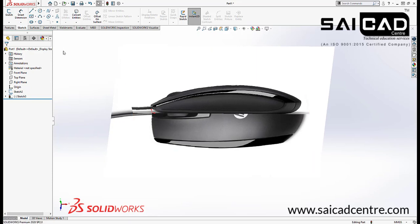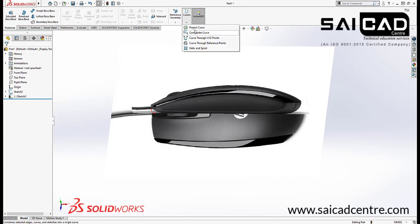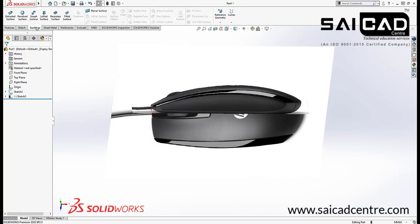So till now in solid modeling, most of the students or most of the people only use the line, circle, these commands, the arc, the rectangle, like these ones. But in surface modeling we will have to create the spline right from here. So we will use in this session only the spline and the style spline, and we will also use the curves from here, the project and the split line. This will be available after we create some splines right here.